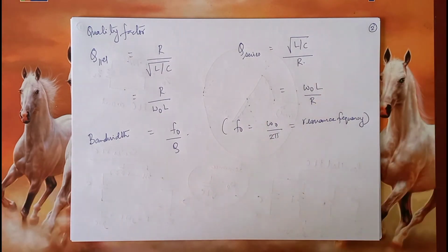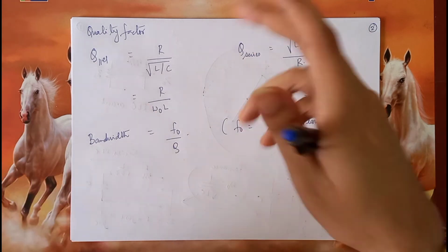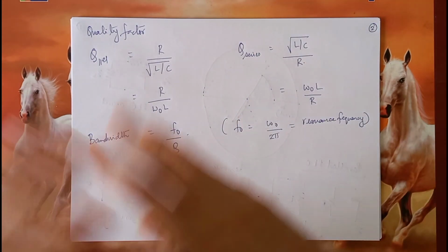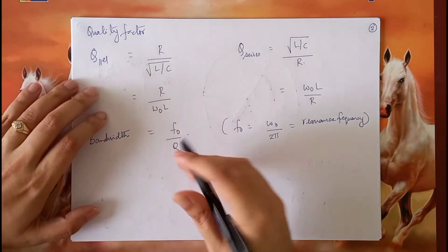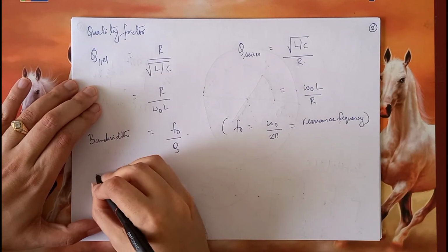And on the other hand, if we want an RF communication system or any other RF system that has to work for a large bandwidth, then in that case, the Q has to be low. So therefore, this is a classic trade-off.